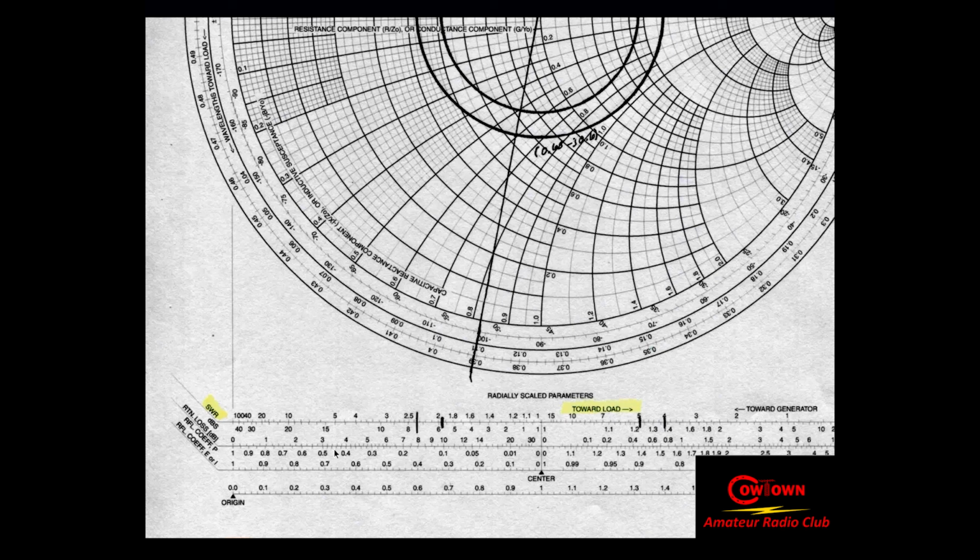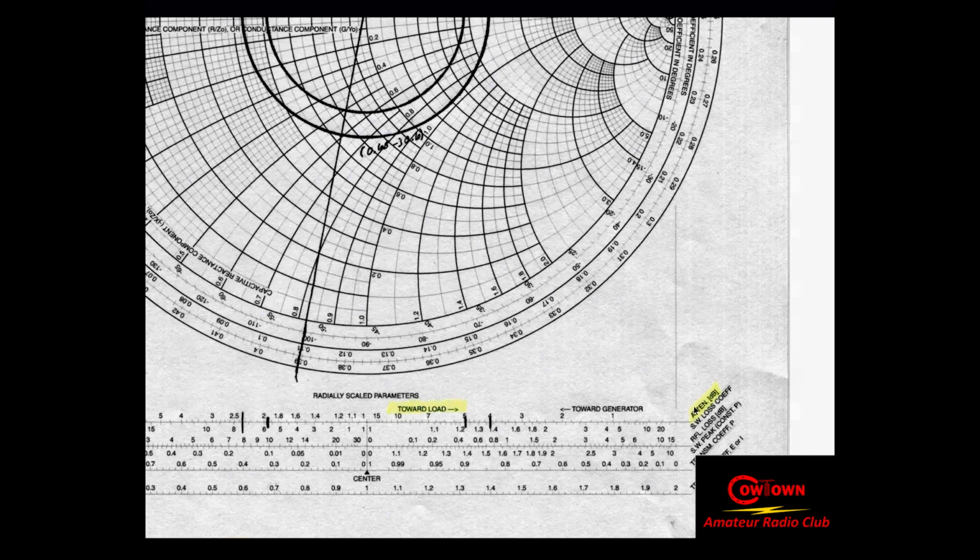Okay, if you look at this second line over here, I've got attenuation. This is my step dB attenuation up here on the top. And the line immediately underneath it is a standing wave loss coefficient. What that coefficient tells us is how much to multiply that 1 dB of intrinsic loss that I've got in my coax by. Well, at one end it's 1.2, at the other end it's 1.4, so average it. Our standing wave loss coefficient is 1.3.